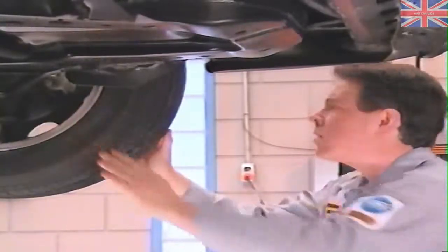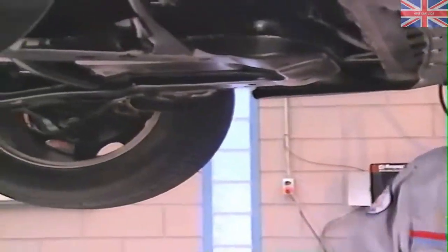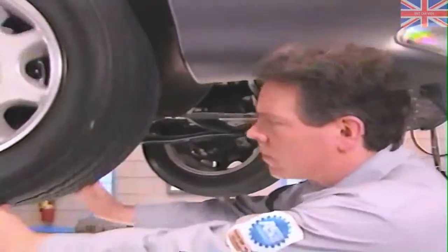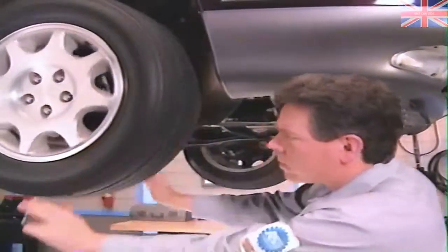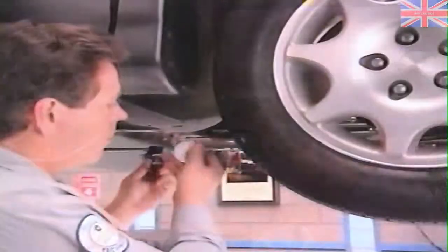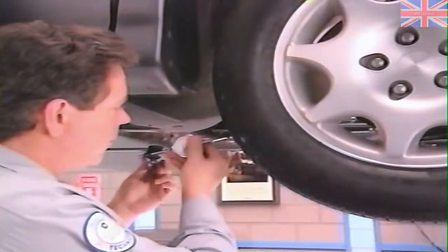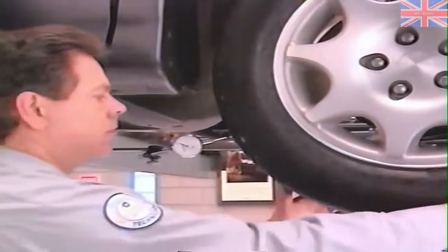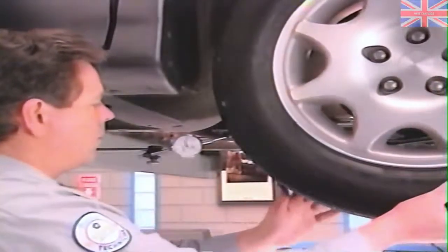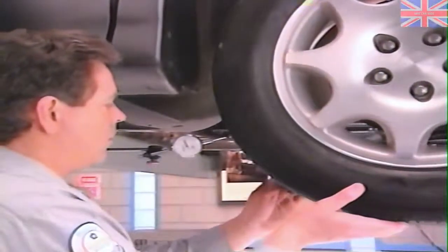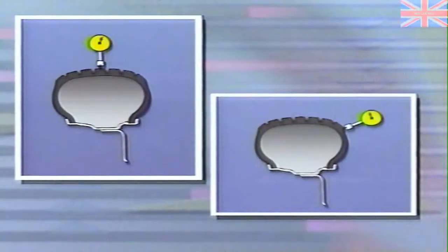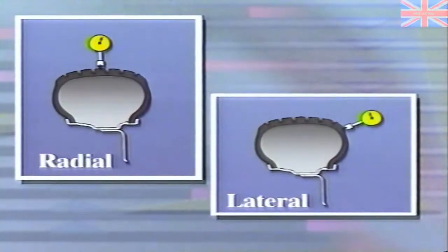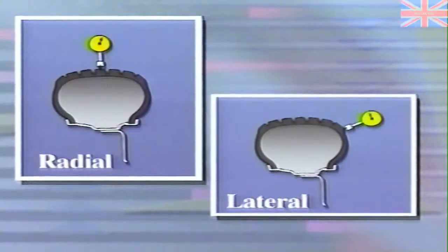We'll first visually check the amount of runout from the front or rear by spinning each wheel by hand, looking for obvious signs of runout. In this case, the right front tire showed obvious signs of runout, so we'll measure that wheel first. In less obvious cases, it might be necessary to measure every wheel. Using a dial indicator, we'll measure radial and lateral runout. Before we measure radial runout, however, we'll tape the tread to ensure a smooth surface.